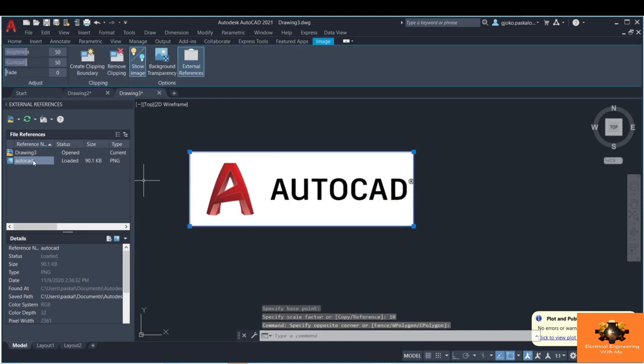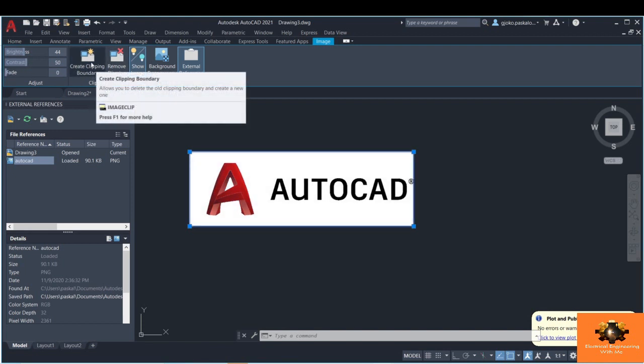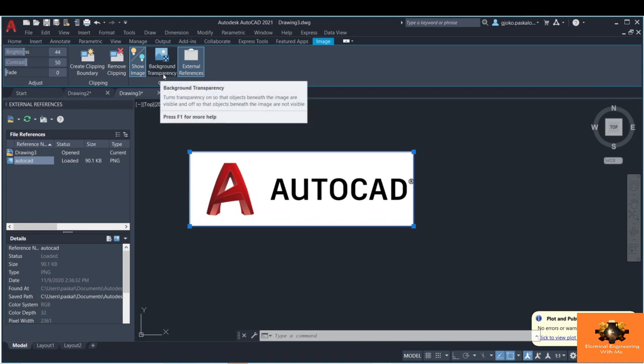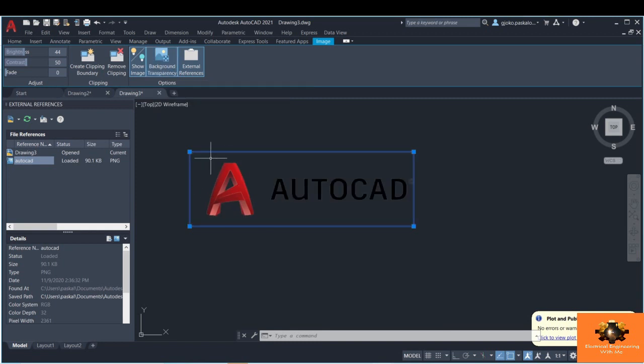If I click on it, you can see that here we have the image as an XREF, and if I click on it, you can see that the menu here will appear. The first is the adjust section. We can adjust the brightness, the contrast, and the fade. We can create a clipping boundary. I showed you how to work with this before, and show the image and turn it back on. Background transparency. For this you need a transparent image, and mostly PNG files are transparent, so when you click on this the drawing will be transparent.